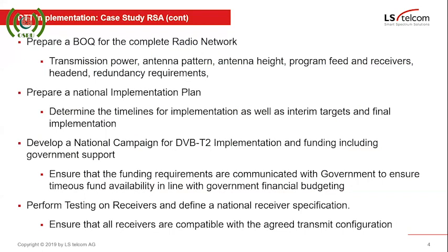I can take an example from Botswana, where they implemented ISDB-T. The ISDB-T receivers were not available, and they have now started to convert some of the ISDB-T transmissions to DVB-T2 transmissions. The main reason for that is that they're the only country in this area having ISDB-T, and everyone else has got T2 receivers.